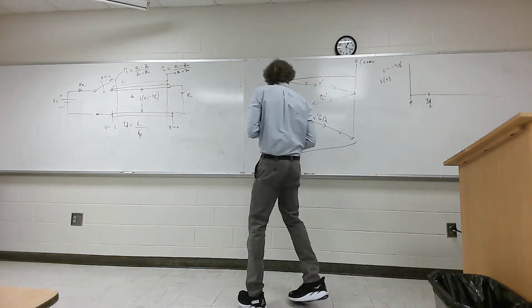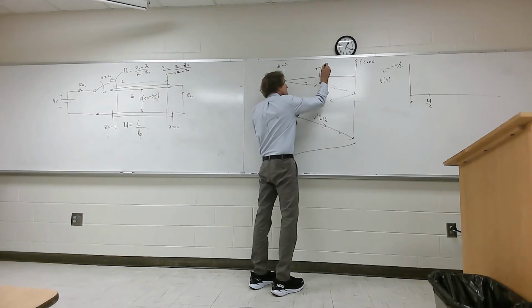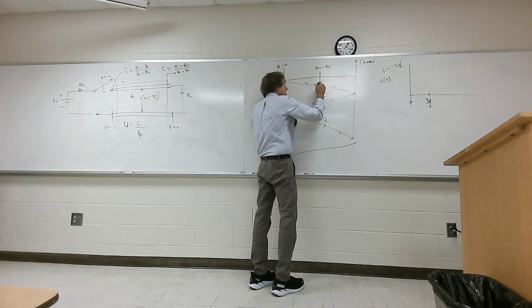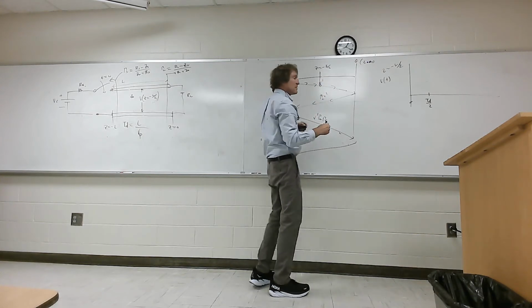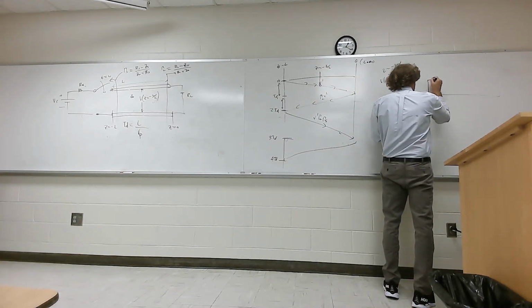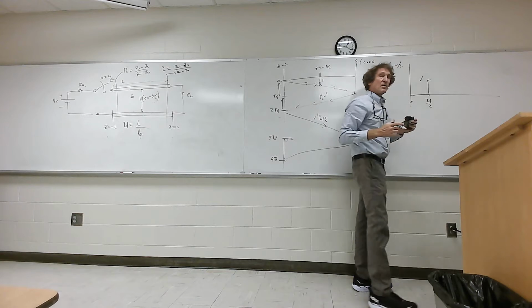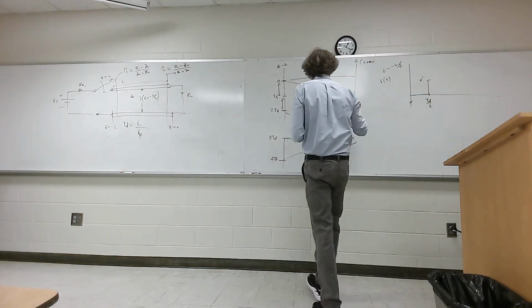The way you do this is simply, you start at the point you want. So I wanted z equals minus L over 2. You go straight down, and you can see that at time TD over 2, this is where V prime happens. So it comes over here, and it goes up to V prime. Y'all follow me?